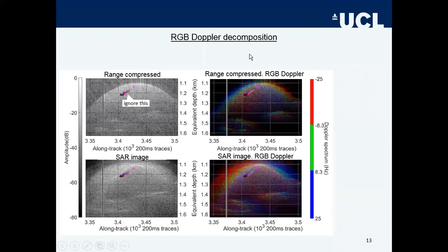So when we make the SAR focusing, we get something really horrible. Instead of collapsing the blue, green, and red into one single profile, what we are getting is the opposite. We are moving this red frequency towards the left, but so much that we are unfocusing. Rather than focusing, we unfocus in this step. Even though we want to make a SAR processing, we get the opposite effect.